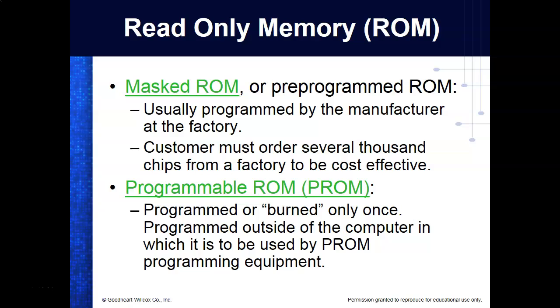We had what they call programmable ROMs. These basically, every storage bit was a little fuse. To store a 1 in there, you'd put it in a programmer. You'd put the ones and zeros in the memory of the programmer, and it would go out there and blow fuses. Once it blew the fuse, it would be a 1. If you didn't blow the fuse, it would be a 0. And that's where the term burning comes into play. Now we don't use that much, but they'll say, you need to burn new ROMs.